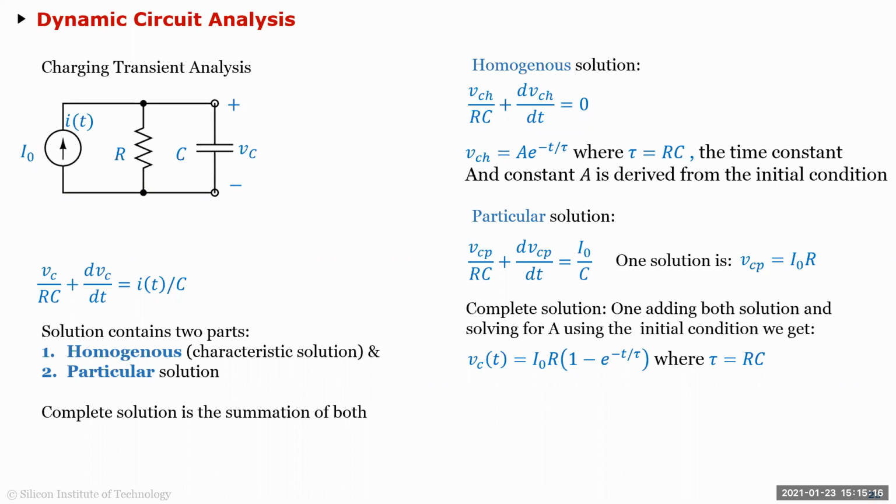So in a network, if you're not changing connections, your poles never change. You can take voltage sources and move them around, but the time constant of the system will never change, or the poles of your system will never change. Only the zeros will change. Okay, and the zeros basically tell you the final value of your step function or whatever you're doing. But the time it takes is all decided by the network. So if you're not changing the RC values or the connections, those things remain as they are.